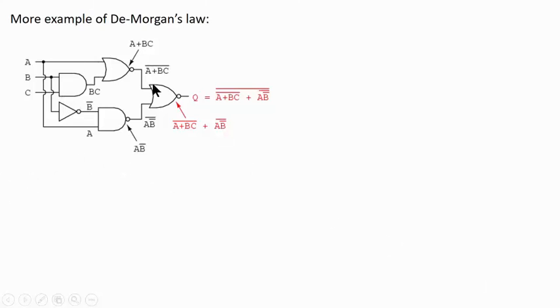So some more example. This three-terminal input is made from OR and NOT gates, right? And this is the output. This is the very final output. And since you need an OR gate, NAND gate, AND gate, and NOT gate, you can break it down based on the DeMorgan.